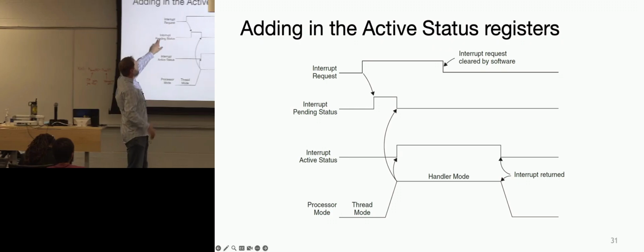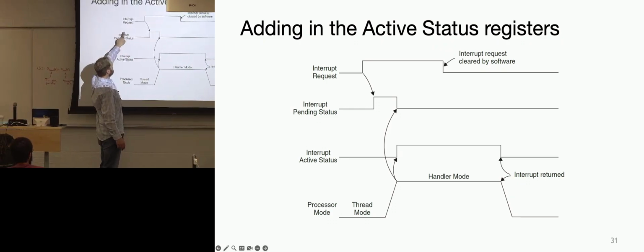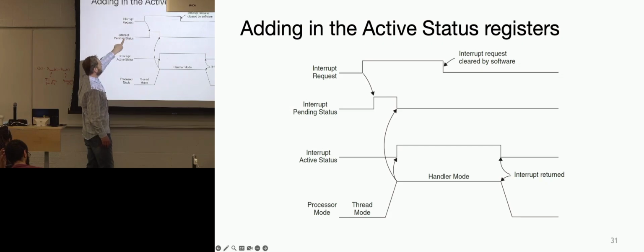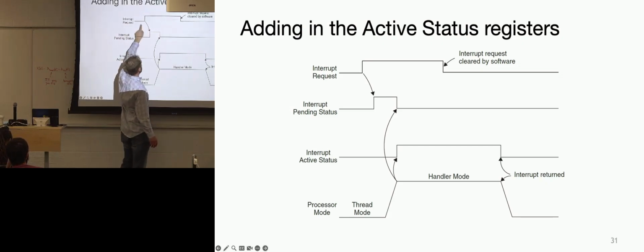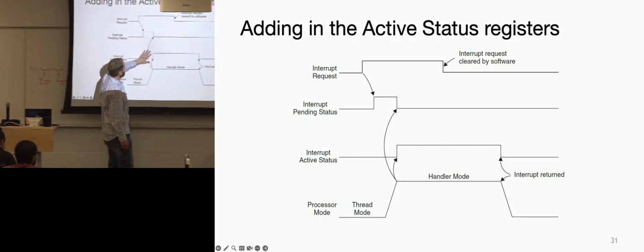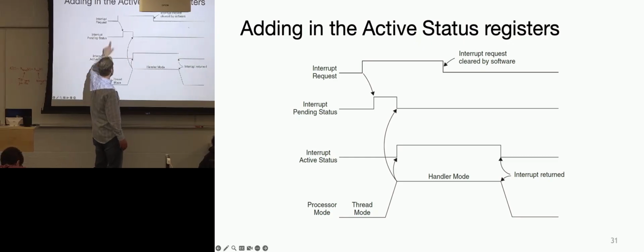All right, so here we go. We'll go through this example just so you guys can all remember. So we have some interrupt request. The interrupt request comes from the peripheral. It goes high. Then your NVIC is going to set pending status. This is a register, and it's going to go high. So between here and here, the NVIC did a task, okay? Then after some period of time, and in this case it's fairly quick, your NVIC is going to take your processor offline.